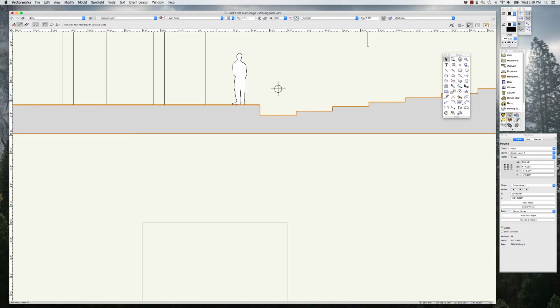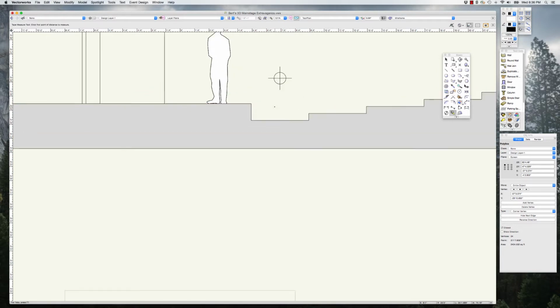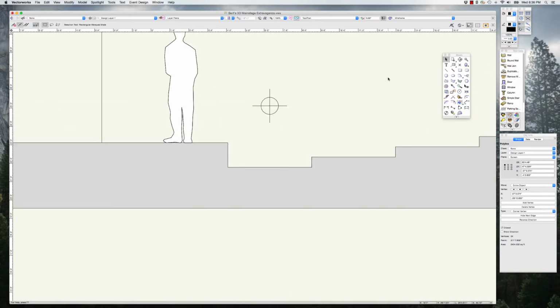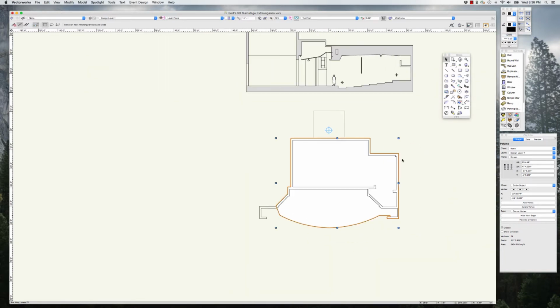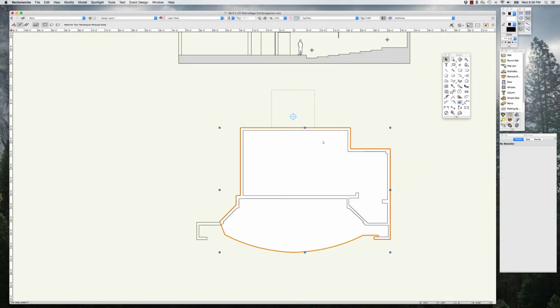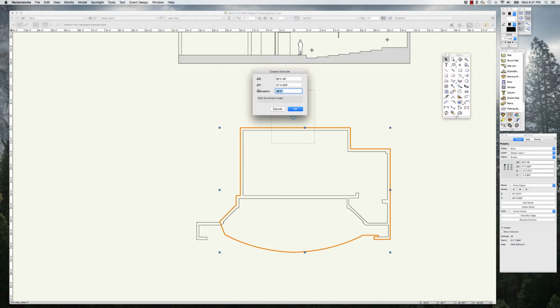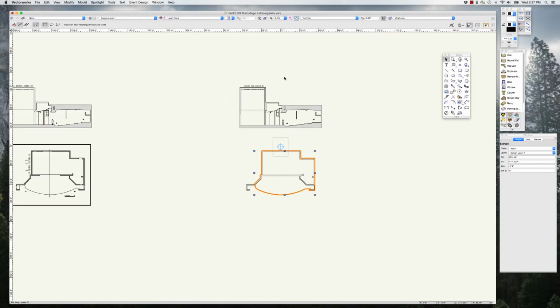Okay. And then we're going to extrude the floor down, and we're going to go down this distance, which I think is 18 inches, but I wouldn't bet my life on it. So, 1 foot 2, close. So 14 inches, not 18 inches. So we're going to extrude this. Model, extrude minus 14 inches, minus 14. Okay. Just going to move this out of the way a little bit.